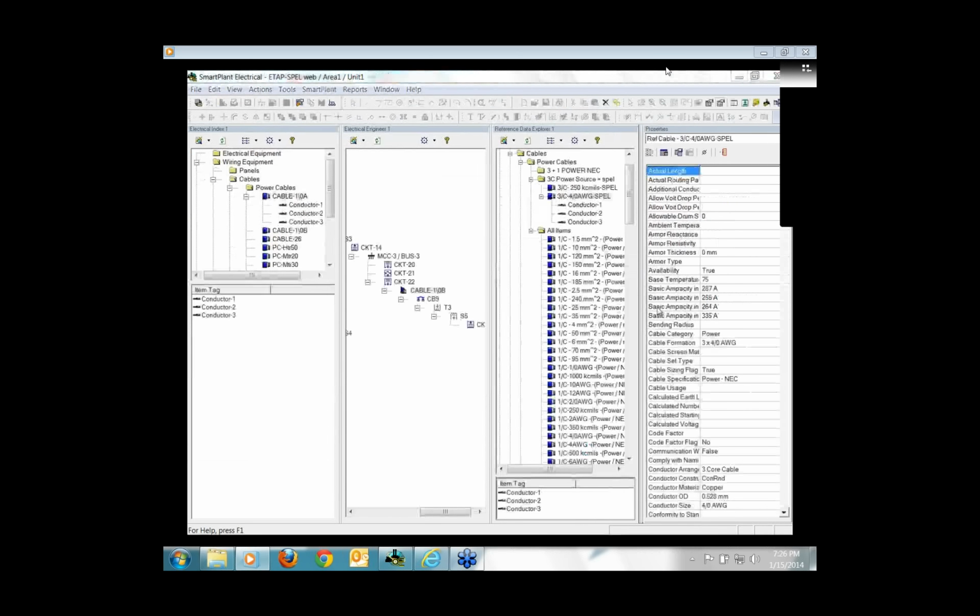You can synchronize the SmartPlant Electrical reference cable with the ETAP cable library of the particular ETAP project if you want to have a commonly shared cable library. This synchronization is optional. If you don't synchronize the libraries, both applications function independently of the cable library of the other application. However, if you synchronize the cable library, each application will identify the reference cables that were specified by the other application. The SLD we published includes cable 1 that associates